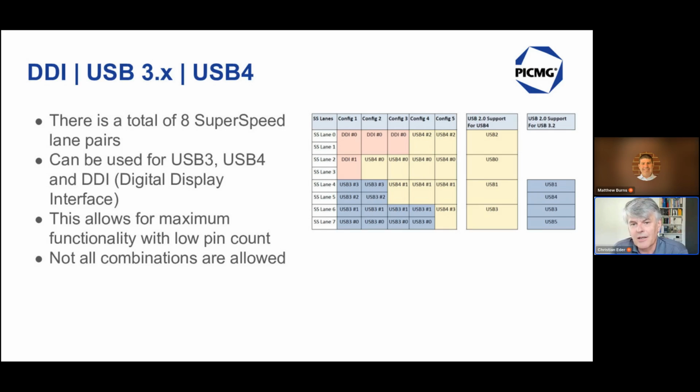And I believe something like configuration 2 is the one which makes most sense nowadays, but there's scalability. A pure USB 4 implementation like config 5 might not make sense today, but of course, the standard must be future-proof. And these 8 lanes can be multiplexed. It's clearly defined. When selecting your carrier board module combination, make sure that the configurations are compatible. So it's a kind of subtype, if you want to call it that way. This allows really for maximum use of the limited amount of pins we have available.